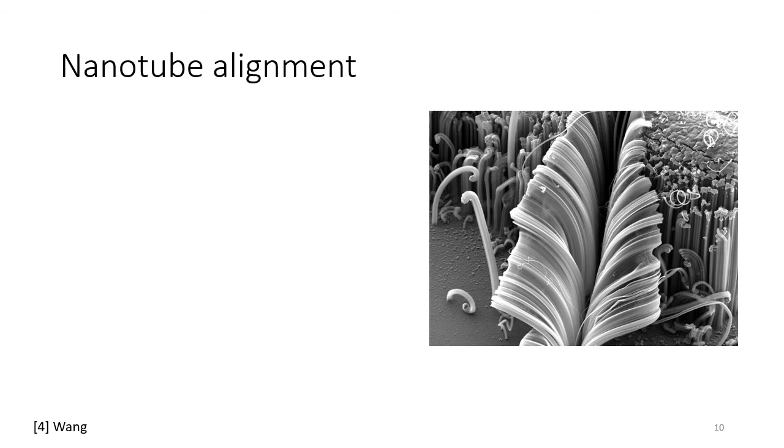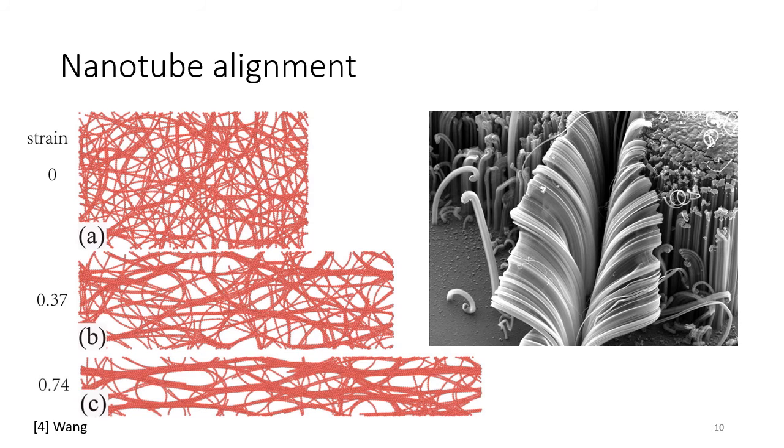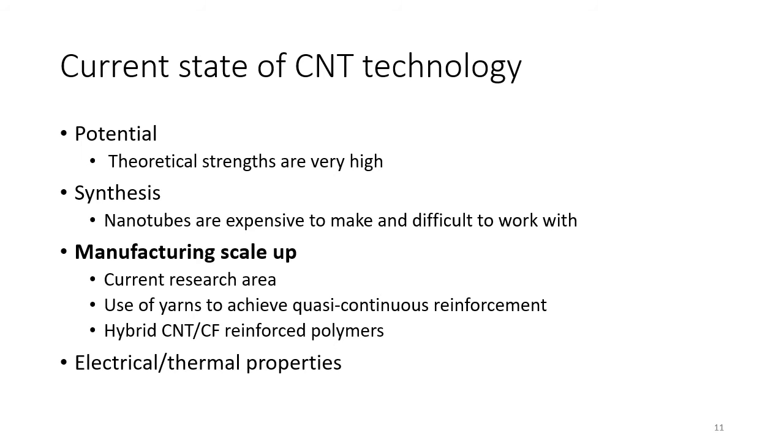This is an SEM image of a CNT forest that highlights the true geometry of these nanotubes, and that it is less than perfect and often has some curvature. This is a depiction of randomly oriented and entangled CNTs, created from something like laser ablation or arc discharge. These CNTs can become more aligned if stretched. So far, we have shown that CNTs are incredibly strong and can be made in large volumes, randomly oriented, or with some degree of alignment.